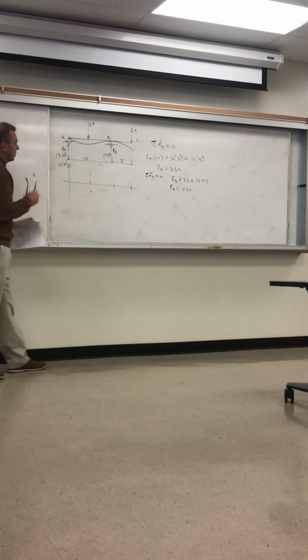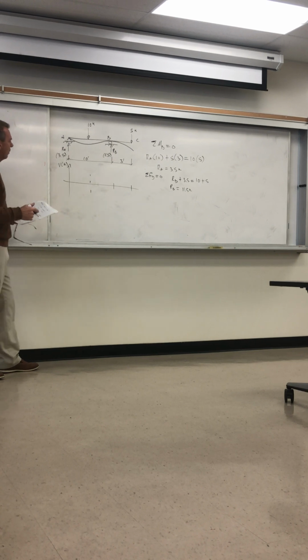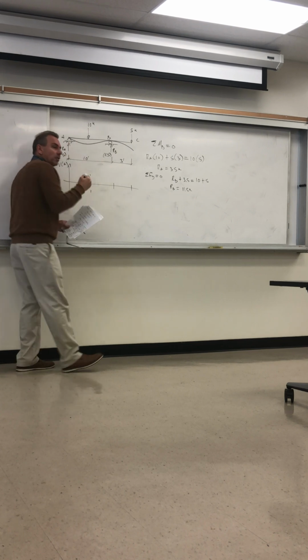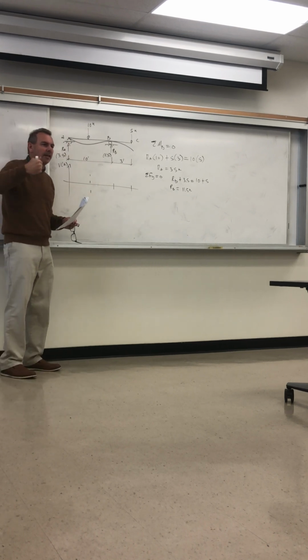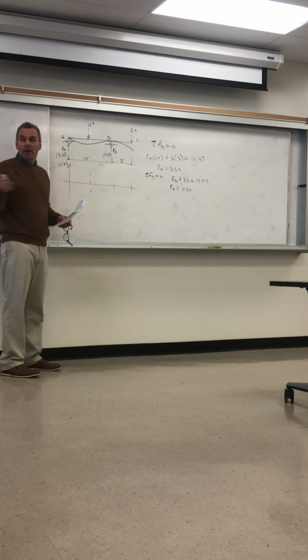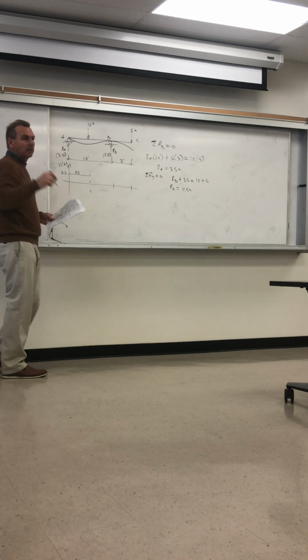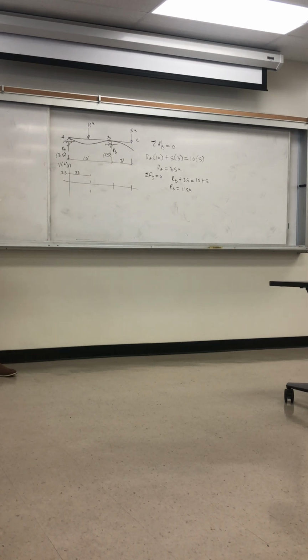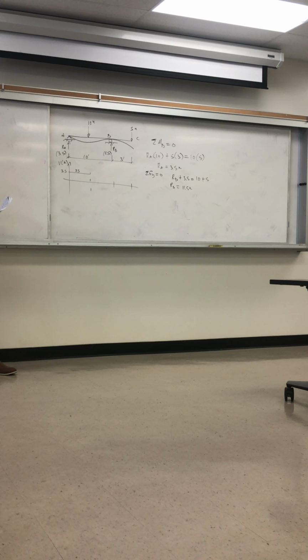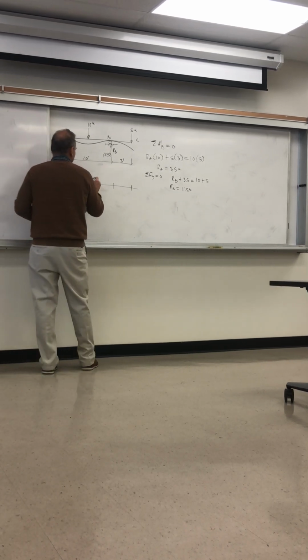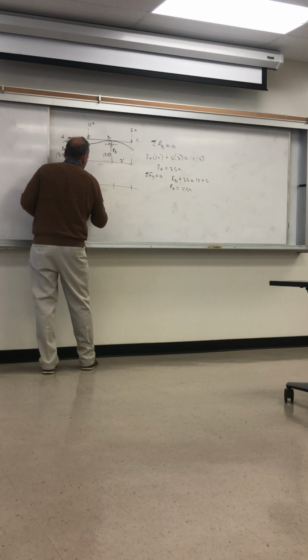Okay, so it starts at 3.5, right? This is the force up at A. And at all cross sections, that is transferring that shear from one cross section to the next. Nothing stopping it or making it change. So it's 3.5 until we get to here. And then as we cross the load in mid-span of 10 kips down, it's 3.5 now, which is up, minus 10. So that gives me a minus 6.5 at mid-span, so it drops down like that.